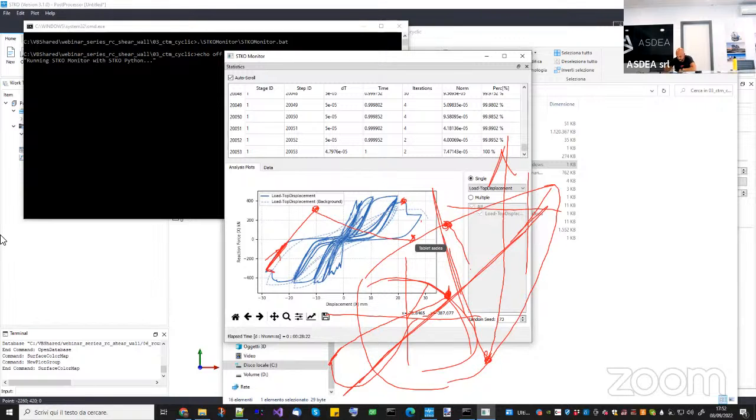So that's why, I mean, sometimes you use a plane stress constitutive model for concrete. So when you say tensorial, this is to distinguish with the plane stress modeling of each layer of a shell, or? No. When I talk about tensorial, also a plane stress model can be a tensorial model. It's not either a scalar model like a uniaxial model or a vectorial model like the microplane model. They work with tensors, not with scalars or vectors, which is a little bit more difficult.